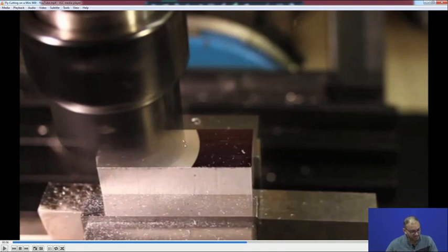That is another advantage, because if you want to create a concave surface with a 3 axis milling machine, then you have to give very small amounts of x, y and z axis motion simultaneously, and that will create a lot of problems at a later stage, because this micro movement in the x, y and z directions will create different types of tool marks. So, you have to remove those tool marks at a later stage. But here, we are using circular motion. That means whatever the radius of this particular cutter is, the same radius of concave surface you can create on any workpiece or optical material without any problem.